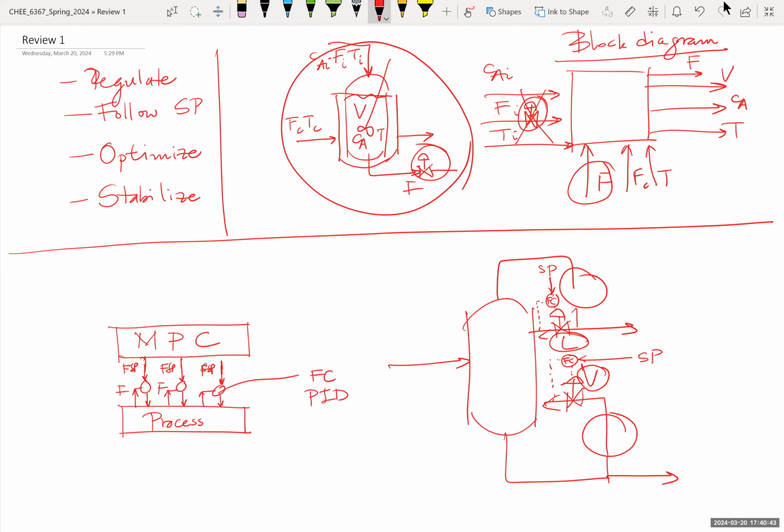Sometimes it's called a SCADA system. That used to be an old nomenclature, which is not exactly model predictive control. It was a lot simpler, but nevertheless, SCADA is supervisory control and data acquisition. So it will be a little bit higher up than the PIDs, but it's not quite MPC. MPC is much more powerful because it does real-time optimization. And there's overlap, but people understand those things well in practice. So MPC would work here to tell what these flow rates should be.